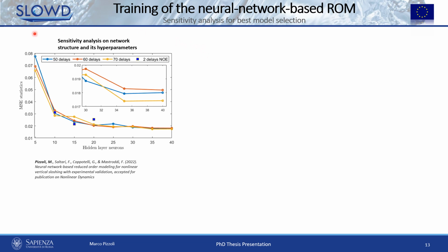And this image shows the error trend on the training data associated mostly with a model named nonlinear finite impulse response model, which involves only the use of the input passing through the delay lines to identify the dynamics of the process.